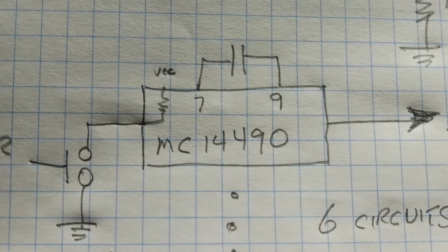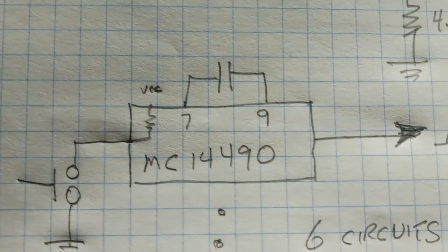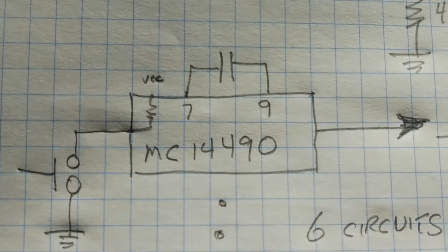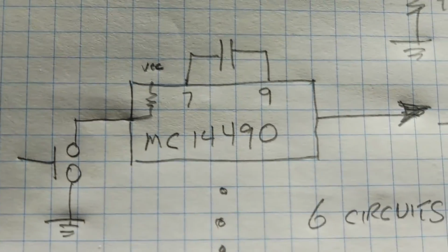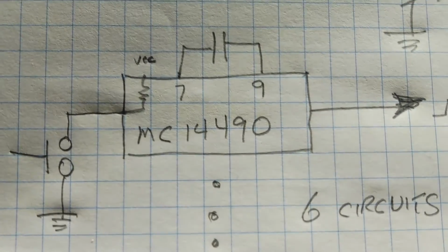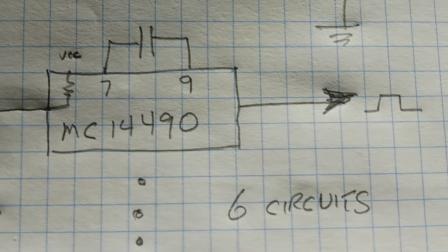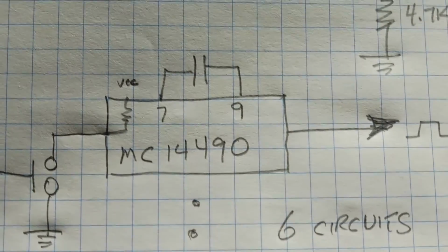It's a DIP chip. So basically you have one external component, that capacitor that runs the internal oscillator, and then there's a shift register inside that shifts from the left to the right output, and every time bounce happens it resets the shift register. So once the bounce settles down, the shift register will get to the output and the output will go high. Now this chip is hard to get.